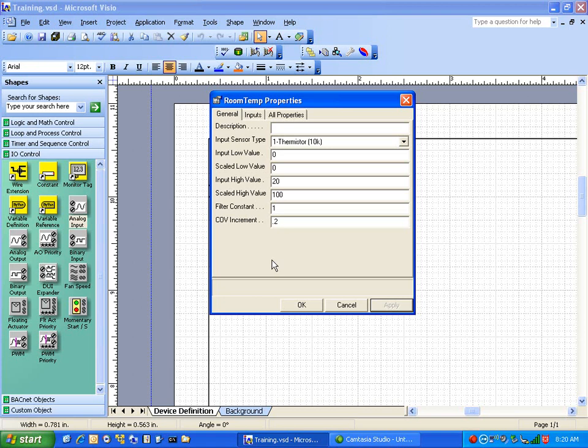As our front end family gets into, like in a G3 world, it's nice because every parameter in this object gets uploaded, right from engineering units and everything, and you don't have to set engineering units up in a UNC at all or in a server. If you make it degrees Fahrenheit down in the controller level, it's going to naturally be degrees Fahrenheit by the time it gets to your graphic screen for viewing, and you'll never have to enter that up in the graphic levels if you do it all down here at the Workplace Tech level, which makes it real easy.